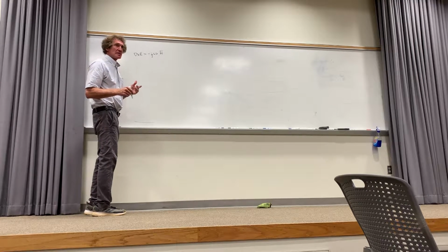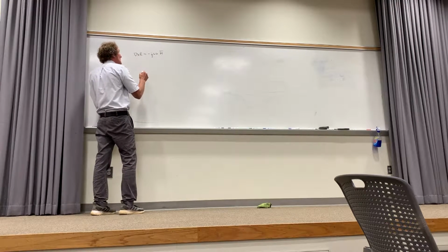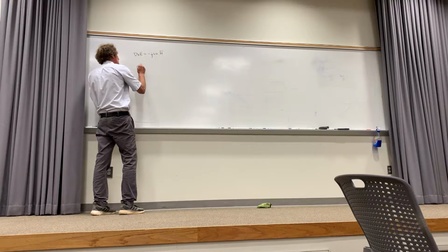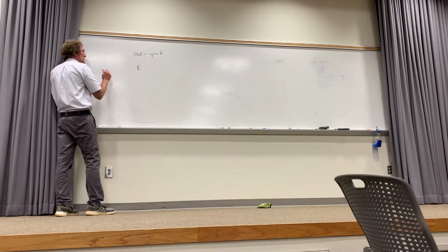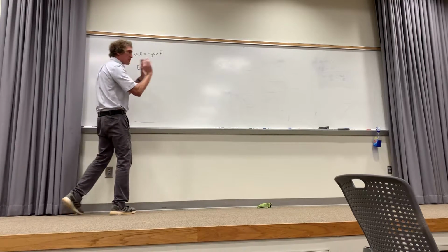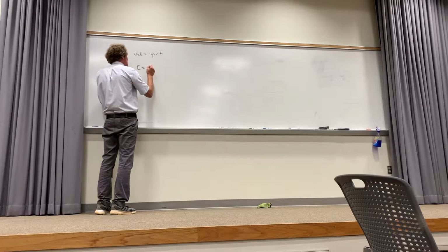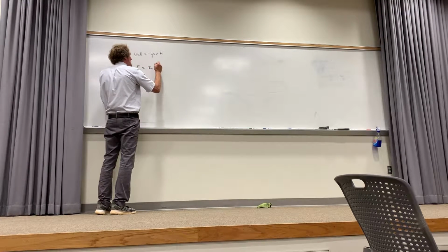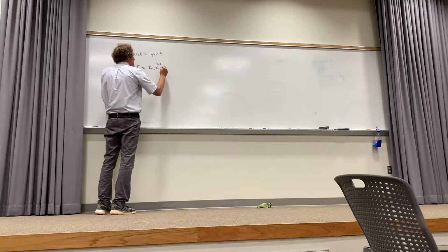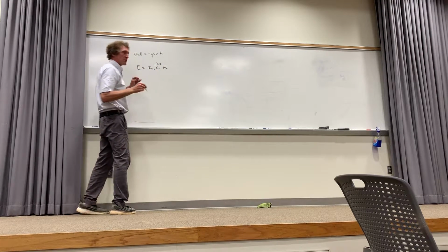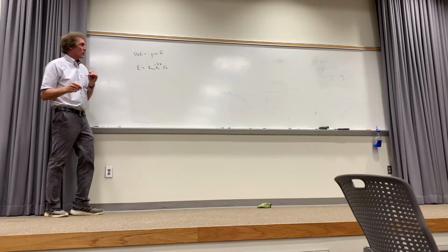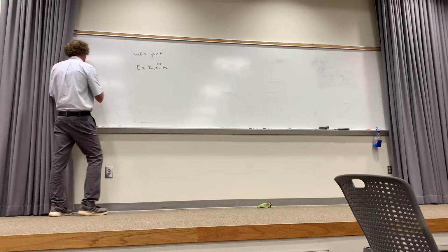Now what we end up doing is this. We have E, right? Let me do it this way. I'm going to just do it for the positive traveling wave. We're only going to take a wave in the positive direction. I'll tell you about the negative in a second. So we have some Ex0 e to the minus gamma z, and it's in the a_x direction. That's our E field, right? Now, what does the curl of E look like?